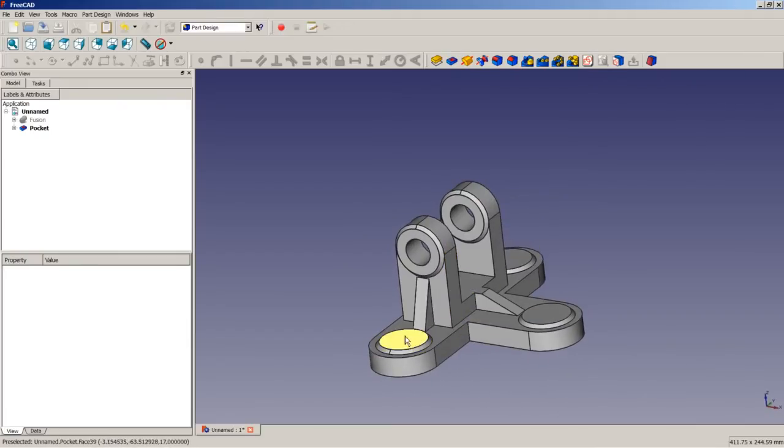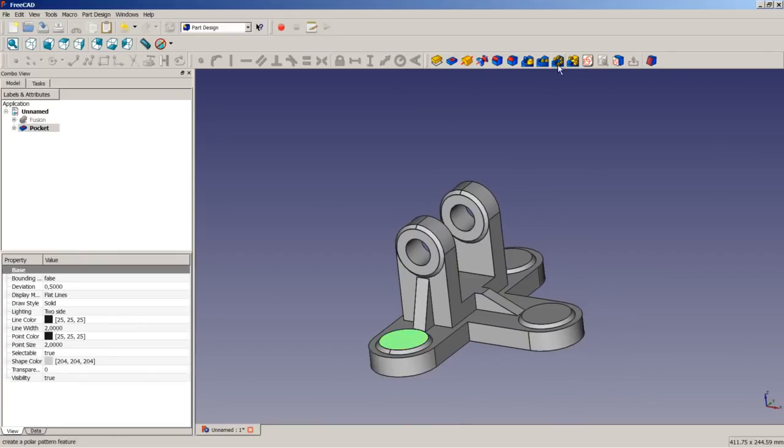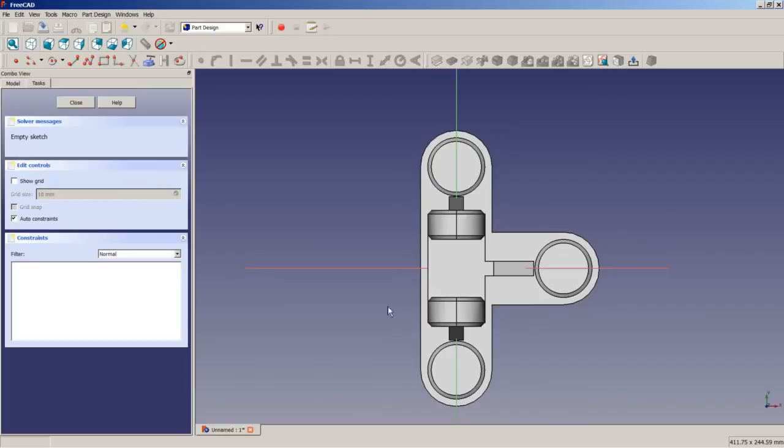And so I will now select this face. I will apply a sketch. I will take external geometry, in this case this circle, and with pocket you have the possibility to do several closed contours. Instead of one closed contour, you have to use, for example, for revolution.